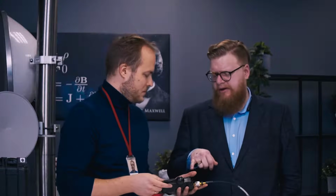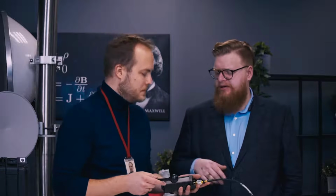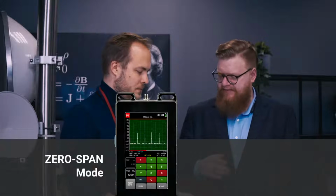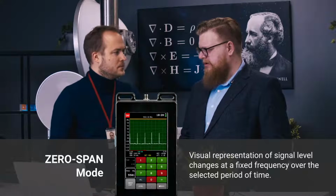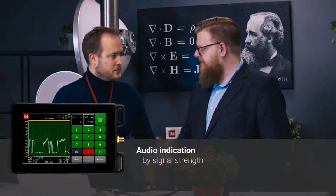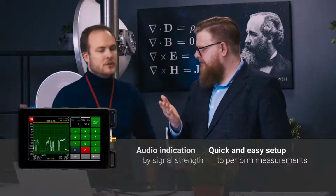With the help of one customer, we actually added features to this that help you. This is a swept tune analog device, so obviously it's not as quick as an FFT device. But we added a zero span mode, and we added a theremin tone. So basically you can use this with headphones or hook up a speaker and move it around, and you hear the proximity based on the pitch. Exactly. And this is also how the customer is using it in the field. It seems to be working rather well too.